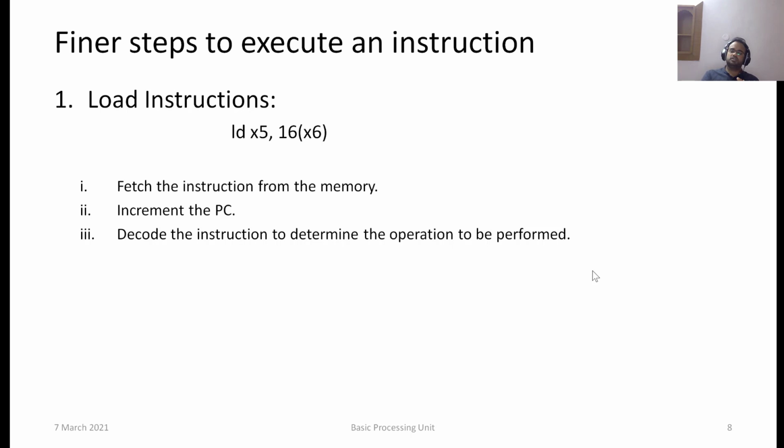So we go about decoding this instruction. Now, how do we decode this instruction? We follow exactly the reverse procedure that the assembler does. What does the assembler do? It picks an assembly instruction and checks for the opcode, function 3, function 7, immediate, RS1, RS2, RD, etc., all these fields, and it creates a 32-bit machine word, right? Machine code. So we do exactly the opposite thing. We take this 32-bit machine code and then look at the opcode, function 3, function 7, etc. And then we would know which type of instruction it is. Based on that, we are going to pick the other fields, whether it might be the immediate field or RS1, RS2, and RD, etc.